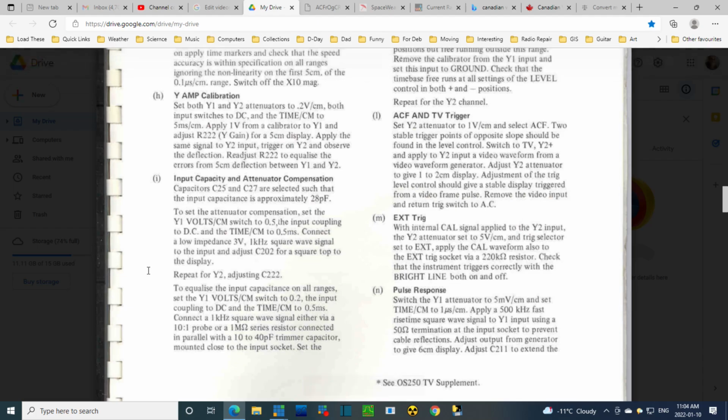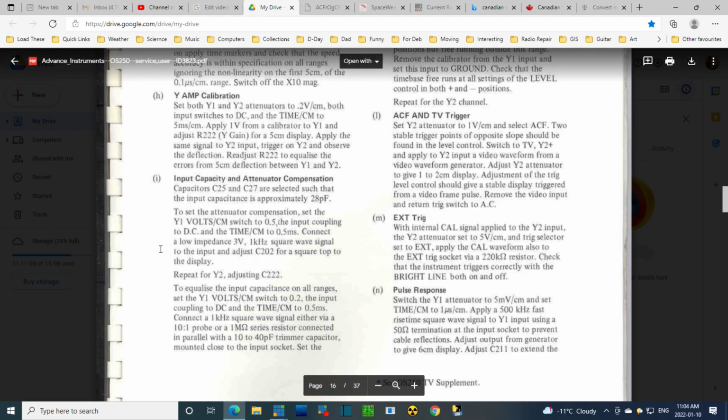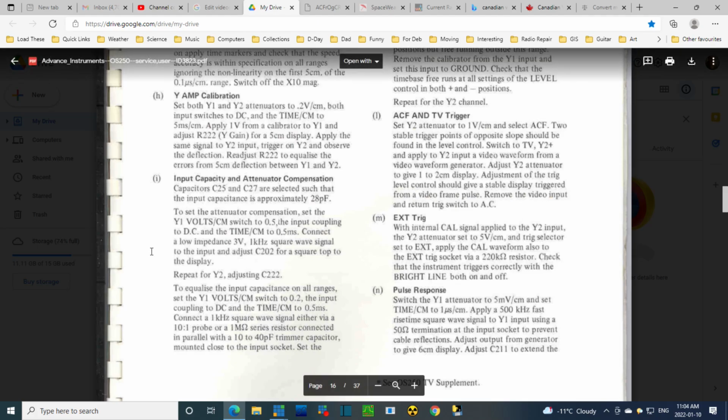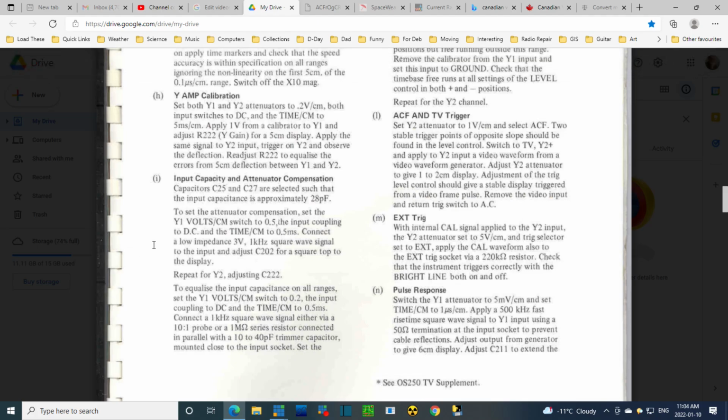Now, why doesn't it rely on its own calibration output? Why doesn't it say that here? I keep suggesting you should use alternate equipment. So I don't think the voltage is all that critical. It's the slope on the line. So not knowing the state of affairs with the calibration output on the scope, I'll use the other calibration output from the other scope. Instead of 3, you know what, I can't do this because I need a larger voltage here because of this setting.